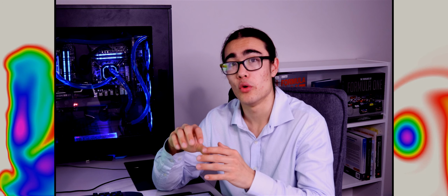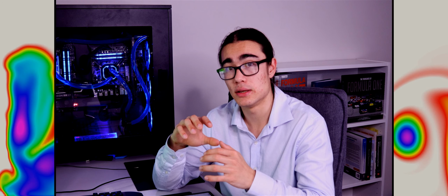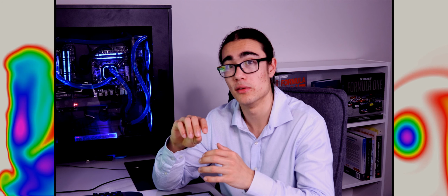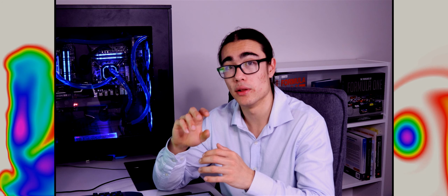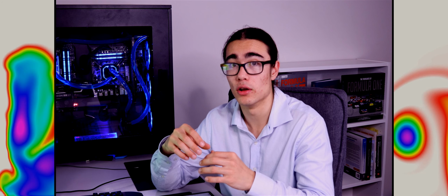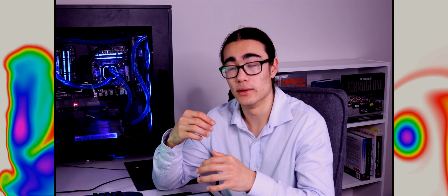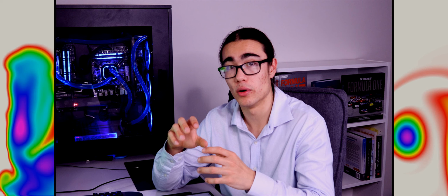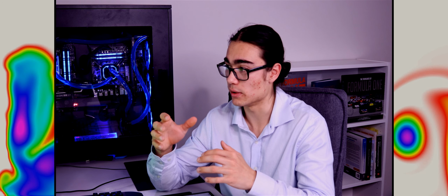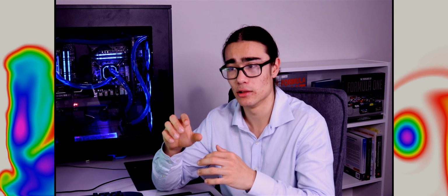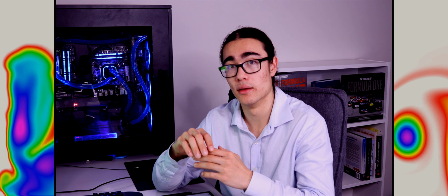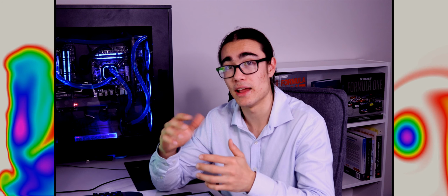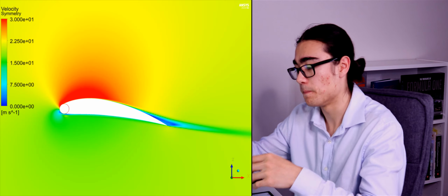Because of this, when you extract more curvature, you're typically going to be thickening up your boundary layer a little bit. You're going to be using a bit of energy earlier on, which means that you should separate earlier on. Now, we've actually separated later, which means that because we've got the Magnus effect working with us, we've actually decreased our losses early on in the airfoil, and that means we've got a bit more energy towards the tail end to hang on to it.